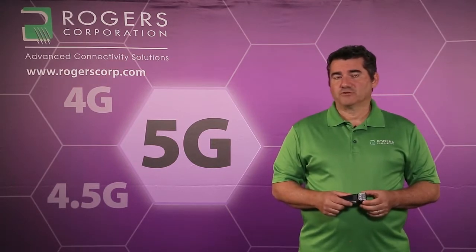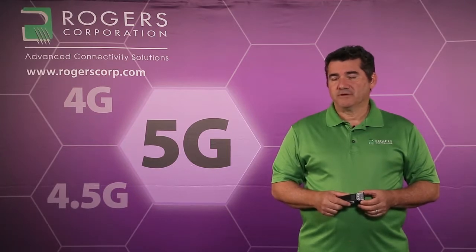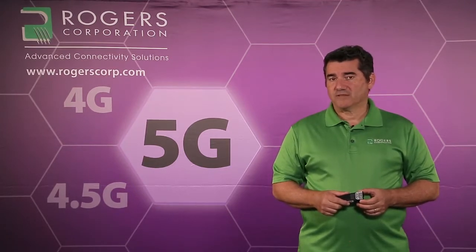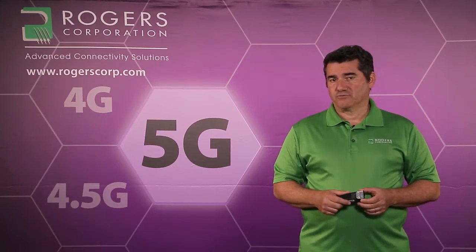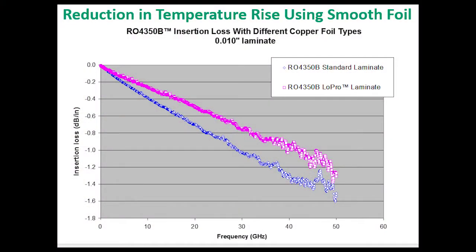Conductor losses are very important to control. Copper roughness in particular is important to understand because it will have an impact on temperature rise. What we're showing here is the RO4350B material with standard copper, which is the blue line, and low profile copper, which is the magenta line. You can see the improvement in insertion loss when you're measuring the material here. In this case, this is 10 mil 4350B material in a microstrip mode. The improvement in insertion loss for a much smoother copper is vital for the RF engineer, as can be seen here measured all the way up to 40 to 50 gigahertz.